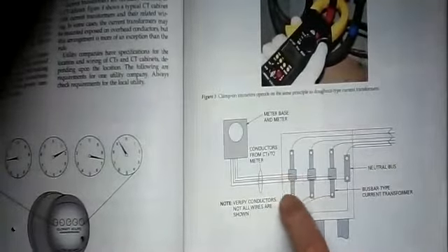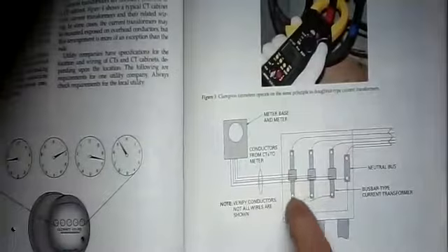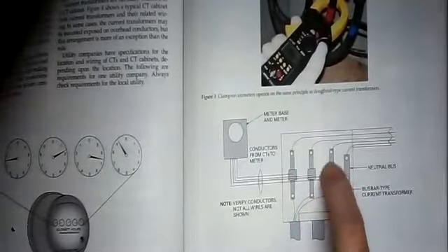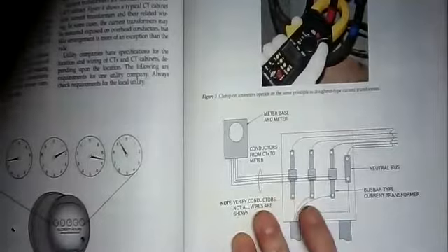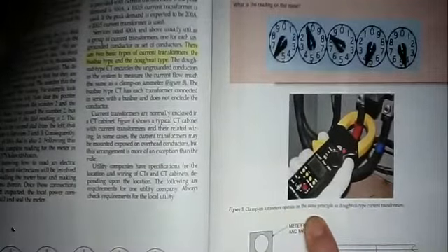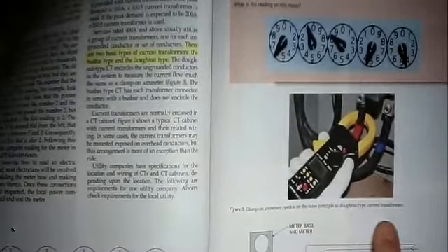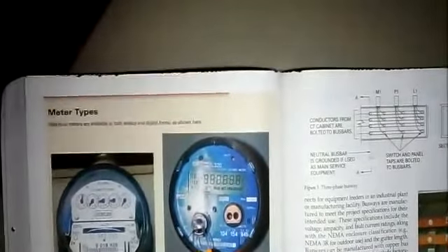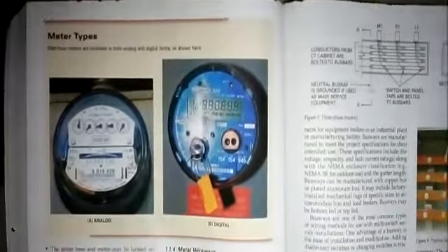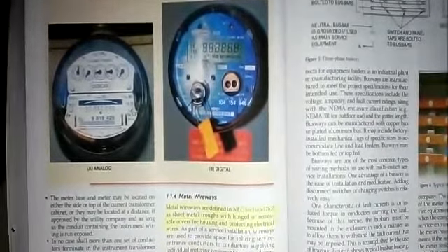It looks like a donut and it goes around the cables or the service entrance conductors that come in. Here they're demonstrating that the CT, the current transformer, is very much like a clamp-on ammeter. Clamp-on ammeters operate on the same principle as the donut type current transformer. It's actually measuring the magnetic field around that wire and interpolating how much current is flowing through the conductor to have that strong of a magnetic field.